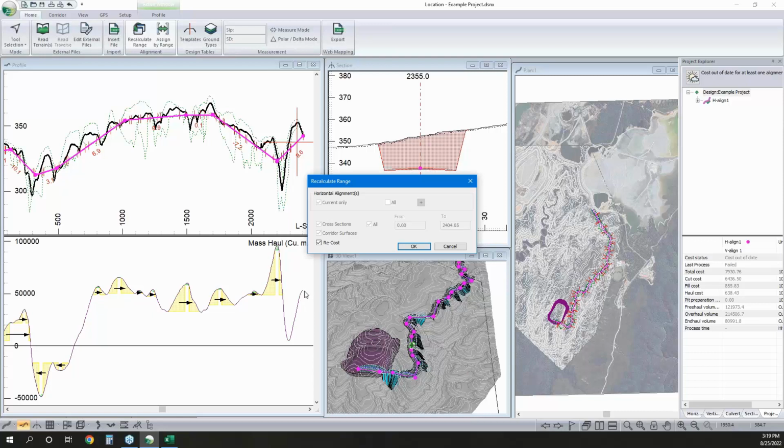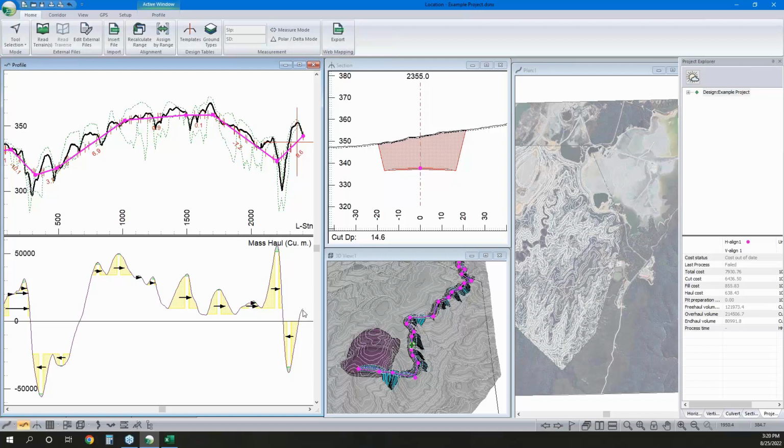And we can see here we've got this surplus of material. And since we're not going to include that organic soil that we're removing in our subgrade, we'll notice that this MassHaul drops down. So we'll have less of a surplus than what we expected. So if you're stripping, it's worth considering that when you're planning and designing your road. And we should see our change. So volume's changed, it makes sense.